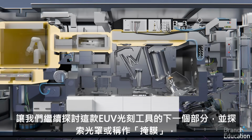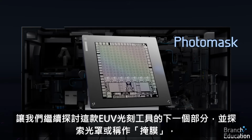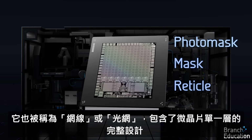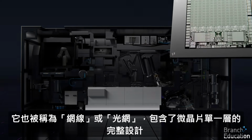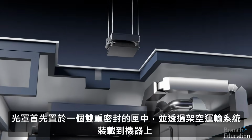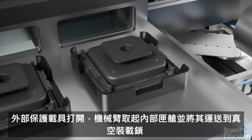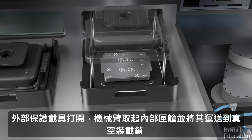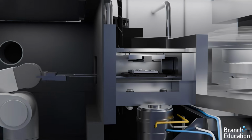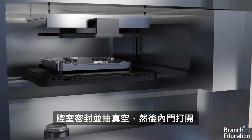Let's move on to the next part of this EUV lithography tool and explore the photomask or mask, which is also called a reticle, and contains the entire design of a single layer of a microchip. The mask starts in a doubly sealed pod and is loaded onto the machine using an overhead transport system. The outer protective carrier is opened, and a robotic arm picks up the inner pod and carries it to a vacuum load lock. The chamber is sealed and pumped down to a vacuum, and the inner door opens.